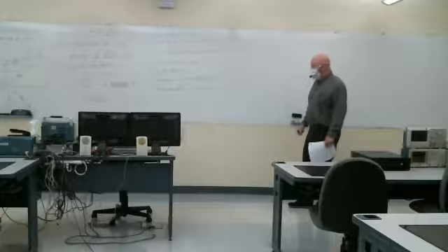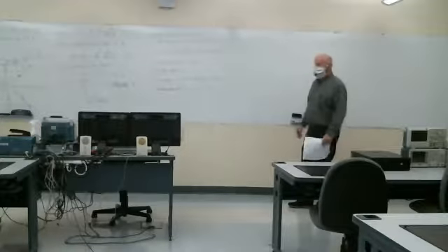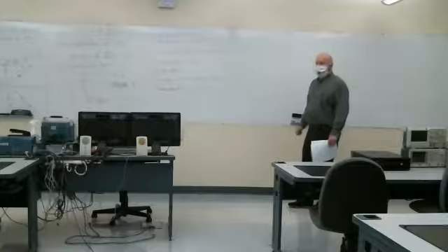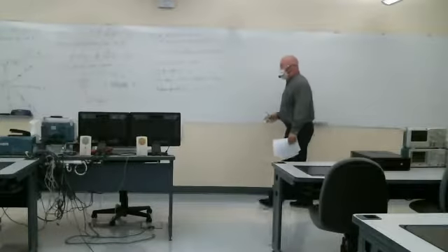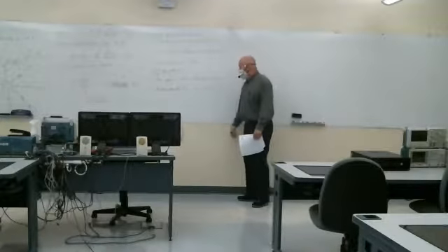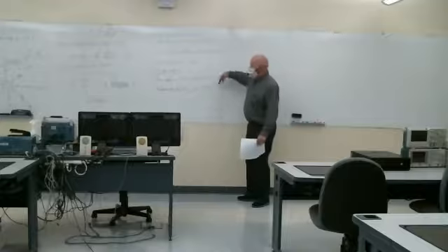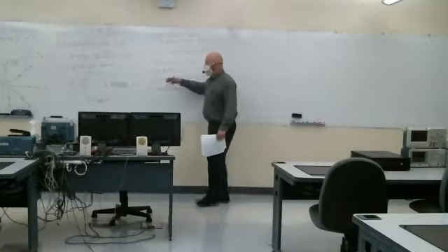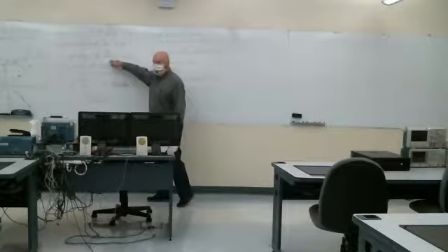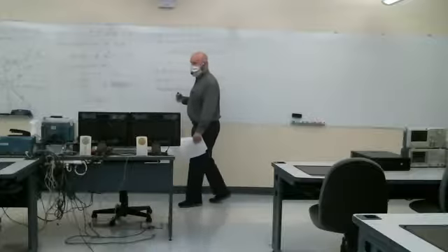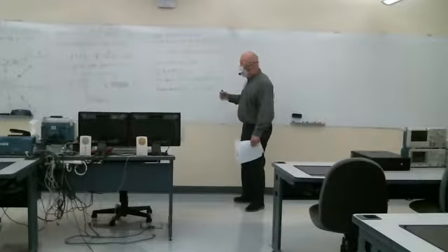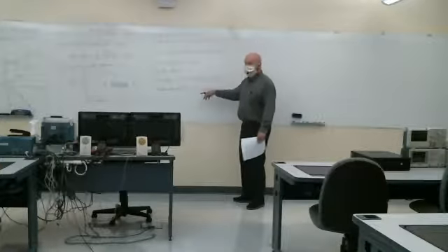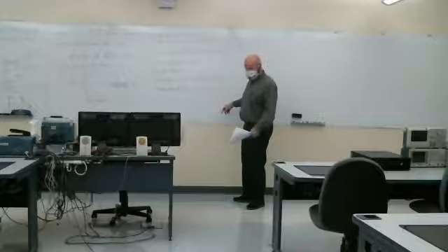Those numbers will typically be between 1 and 100, depending on the material. Now, you don't plug the relative permittivity into these formulas. You have to calculate the permittivity, but that's easy: the actual permittivity is just the relative permittivity times epsilon 0.